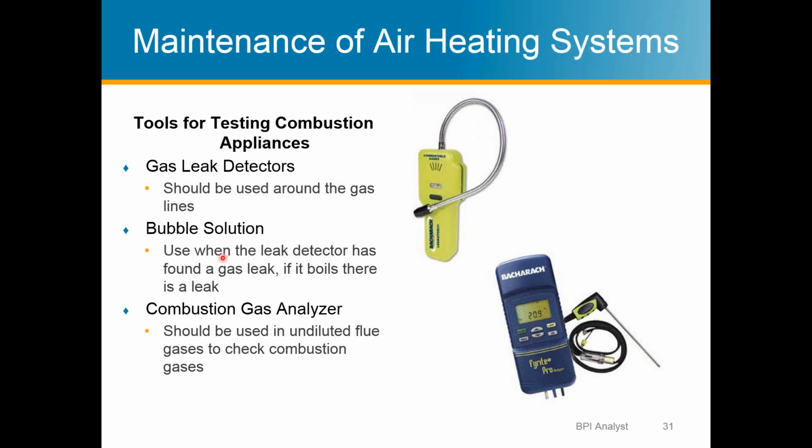So a bubble solution confirms that it's a gas leak and not a false positive, and it also gives you a relative size. The gas leak detector will go off louder and faster typically, but a bubble solution will tell you just how small it is. It's a good indication anyway.